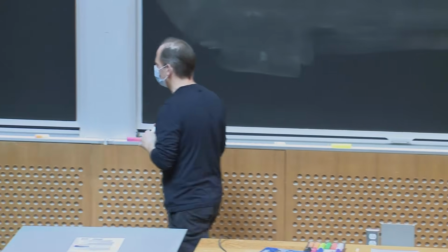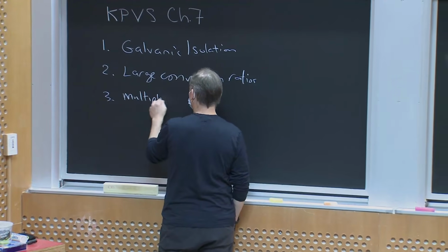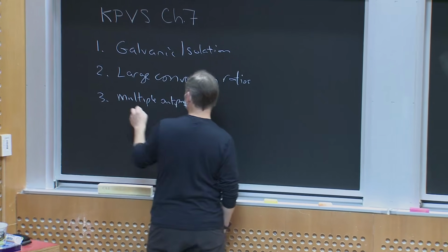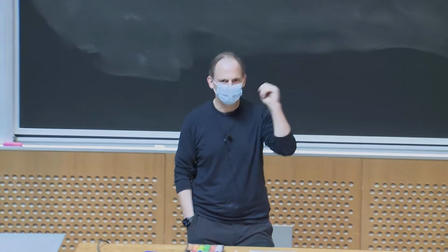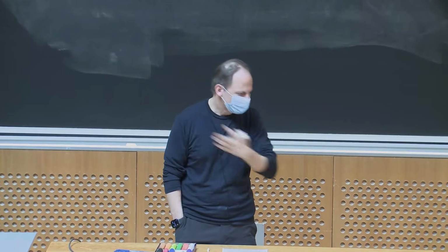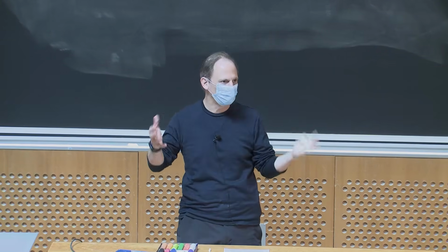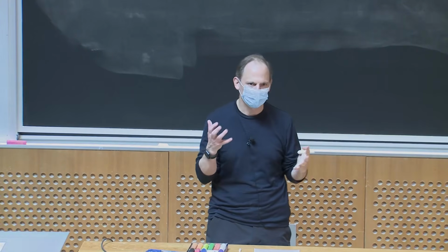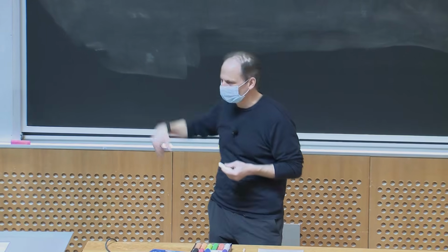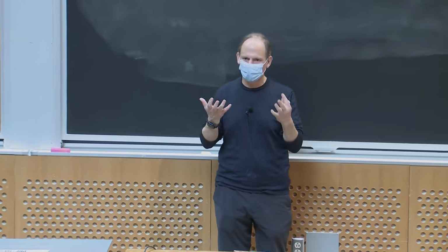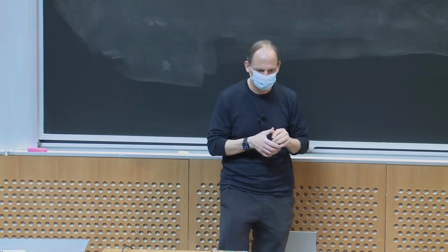Okay? The third reason that's very common is that we can do multiple outputs. So, a typical power supply for your computer, maybe you want plus 12, plus 5, minus 5, so you can supply a whole bunch of different stuff at once. And yeah, you could build separate power converters to do that, but wouldn't it be nice to build one converter that does it all in a more compact form factor? Having transformers at our disposal lets us do that. And lastly, which I don't put up here, it turns out transformers just open up the range of topologies and structures you can put into a converter, and thereby help you design some interesting things.